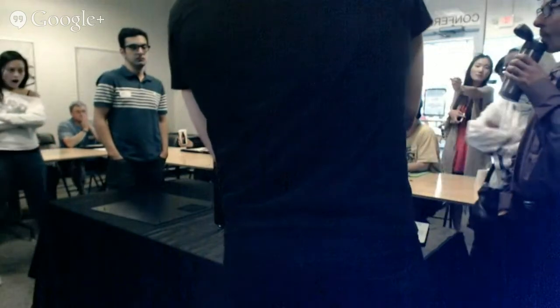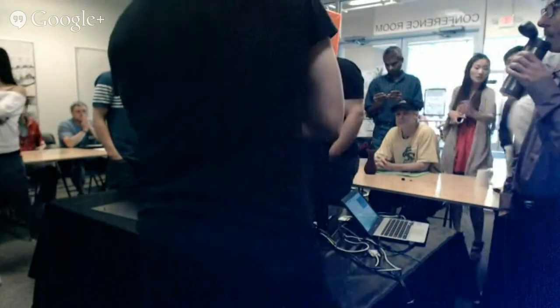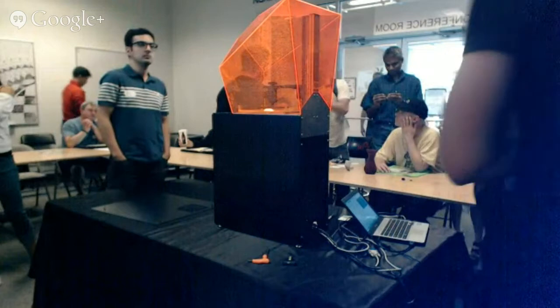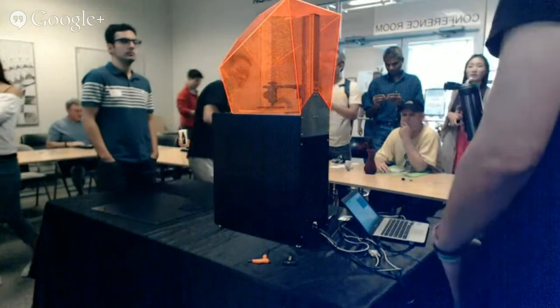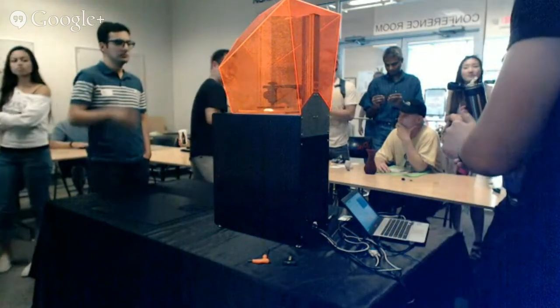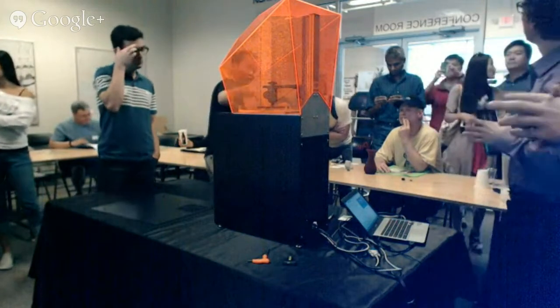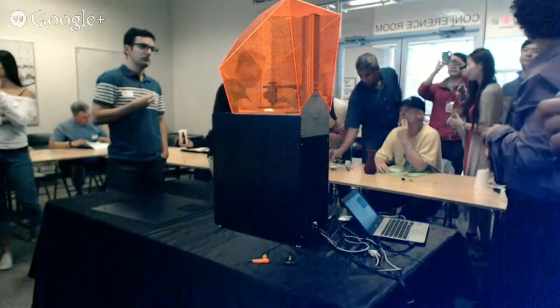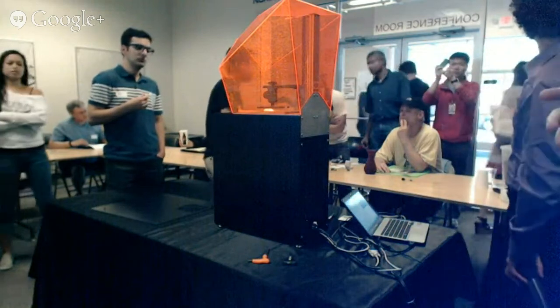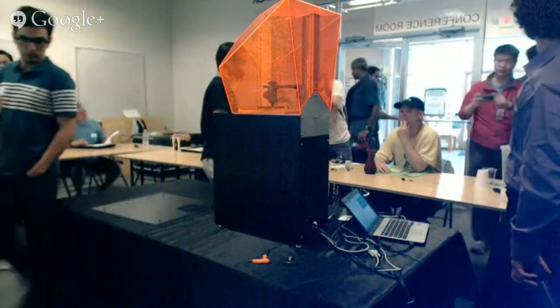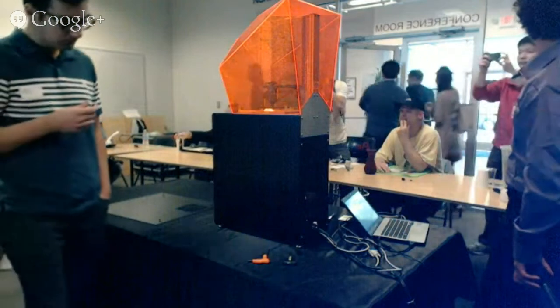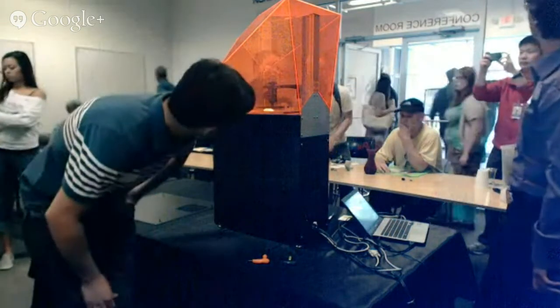A couple of things that'll break your vat is if you print unattended and then find that you didn't lift enough. If you watch this, you see there's a cycle that it's going through right now. It's going to lift to try to release, right? And it's got to lift high enough to pop the part off the vat. If you don't, you're going to re-expose the same layer against the vat.